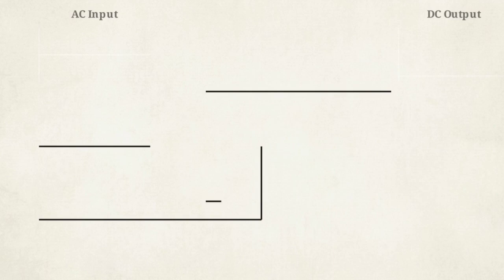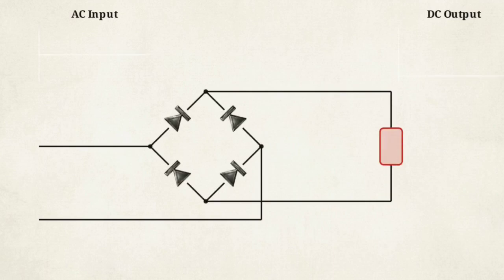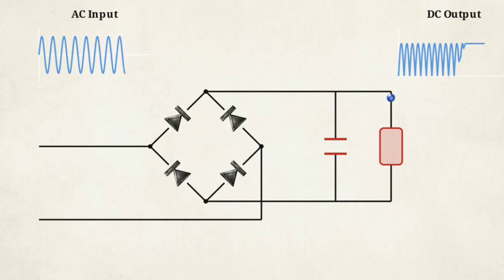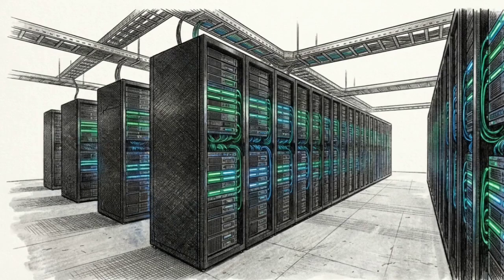The engineering solution is full-wave rectification, which utilizes a precise geometric arrangement of 4 diodes known as a bridge rectifier. Instead of blocking the reverse flow, this bridge routes those backward-moving electrons through an alternate path, effectively forcing them out in a forward direction. By adding a capacitor to the end of this circuit, those pulsating forward humps are smoothed down into a clean, flat line of direct current. By strategically arranging these atomic barriers, engineers tame the volatile oscillation of AC power into the highly stable DC supply required to run modern electronics.